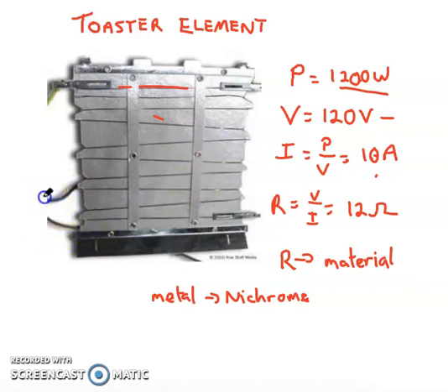So imagine I have my plug over here. Well, that plug is a cord, right? And inside is wire that's conducting electricity, and that's usually going to be copper. I don't want the copper wire to warm up. I just want it to be a pathway from the voltage source to the load. So the trick is to get this wire to have a higher resistance than the cord wire, but a low resistance in the grand scheme of things.